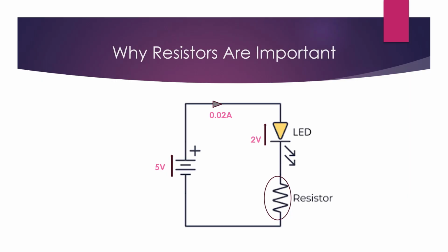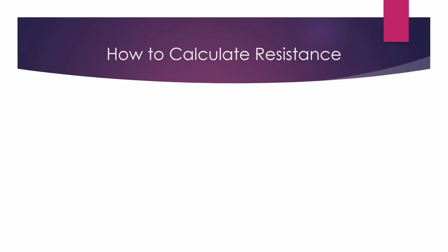Resistors are also used to divide voltages, create timing circuits, set gain in amplifiers, pull up or pull down logic pins. To figure out what resistor to use, we apply Ohm's law: voltage equals current times resistance. Rearrange it to find resistance: resistance equals voltage divided by current.